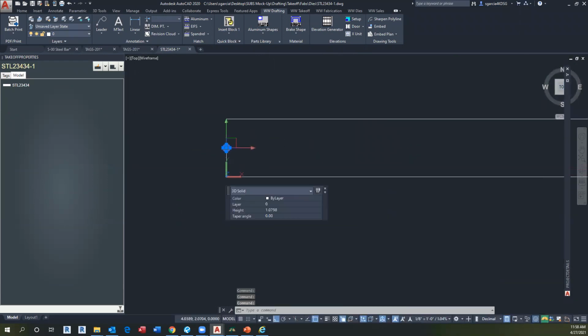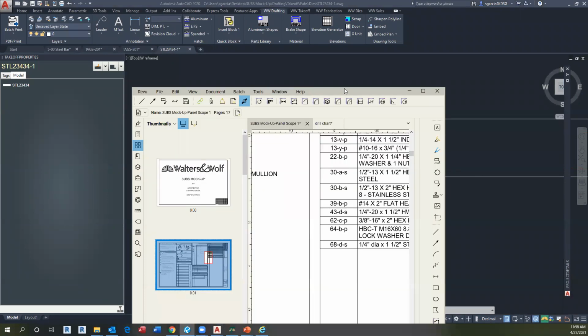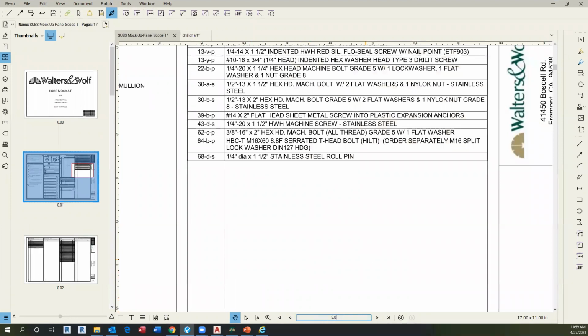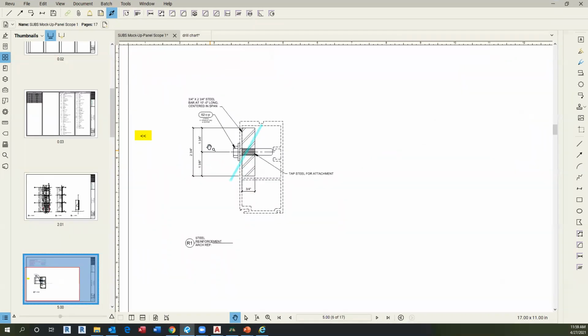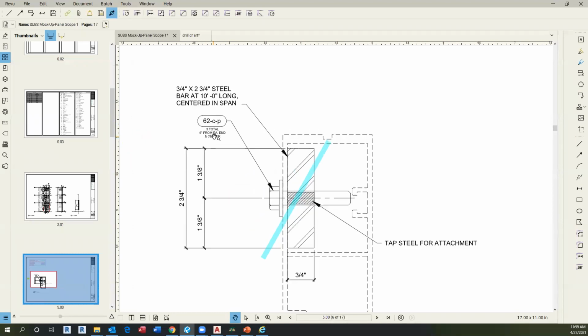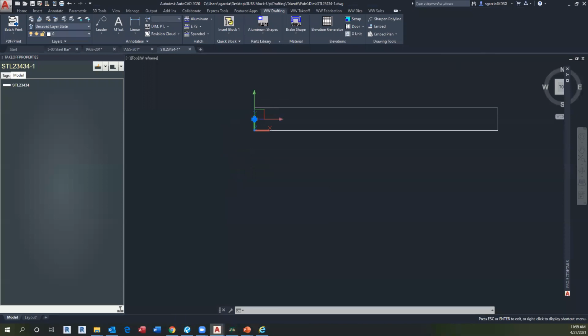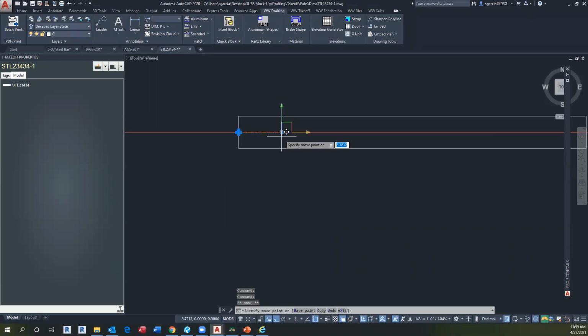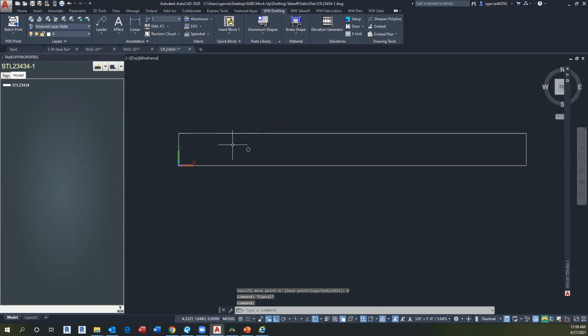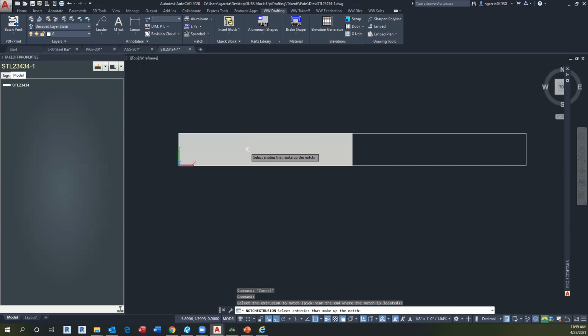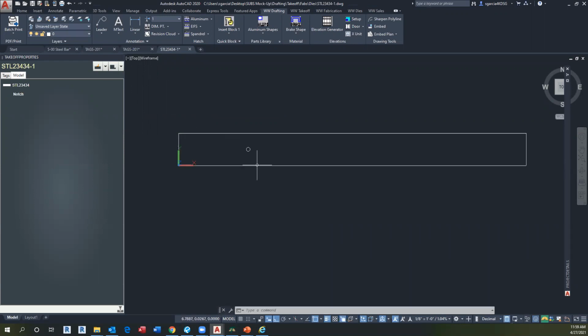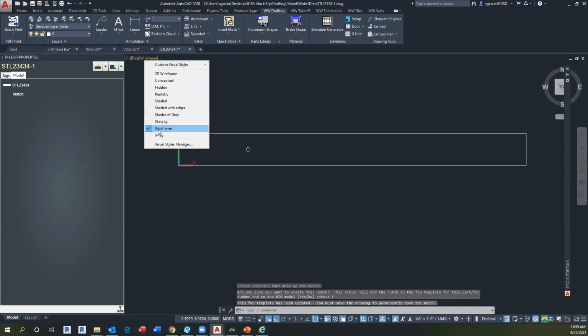Okay. So now what I need to do is go back to my detail just to make sure where that place is. So it's from detail 500. It's a total of 3, 6 inches from each end and center. If that's the case, I need to move this hole 6 inches from the end, and I have the right location for my hole. So if I hit notch and select the extrusion to notch, and then the second click is what I'm notching, and it asks me what I want to do. And there you go. I have my notch there.